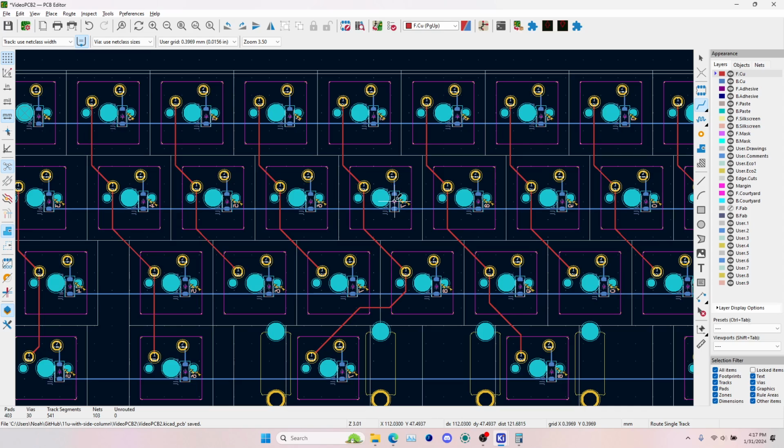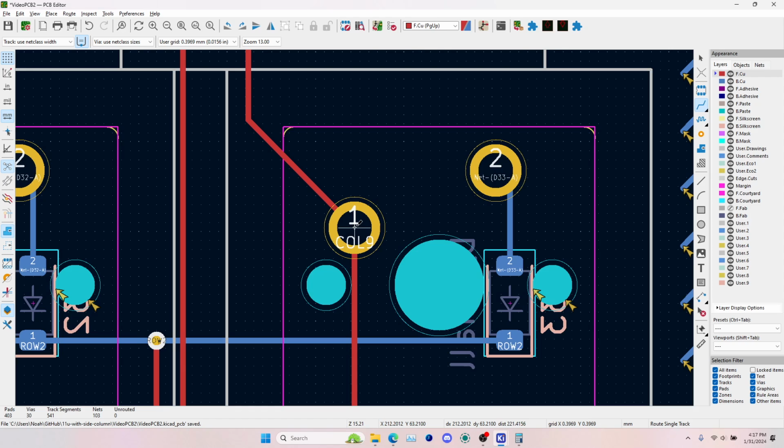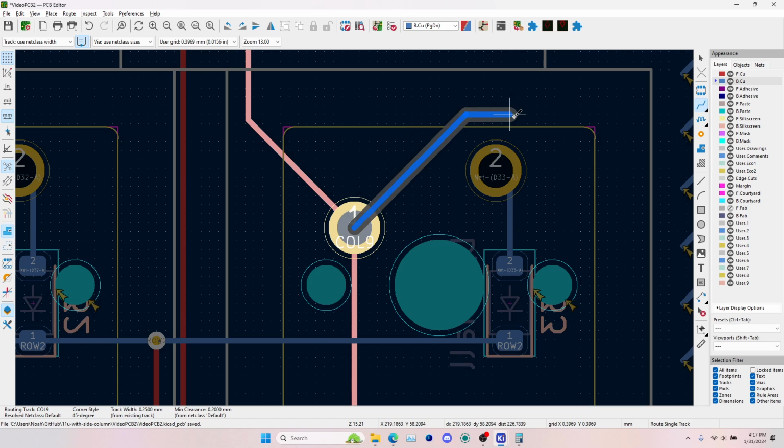Now, buses usually are bad design. Electrically, they're not great. But we can do it in this case because it's a very slow signal. This matrix scanning might happen 1,000 or 5,000 times per second, but 5,000 times per second electrically is not very fast. So we can create these big horizontal traces that all line up on top of each other.